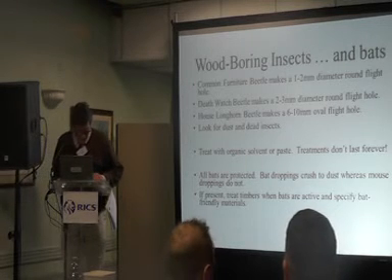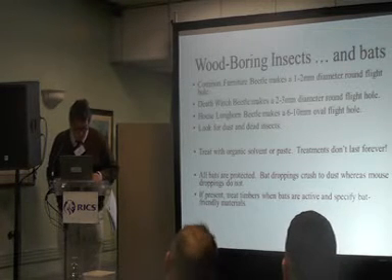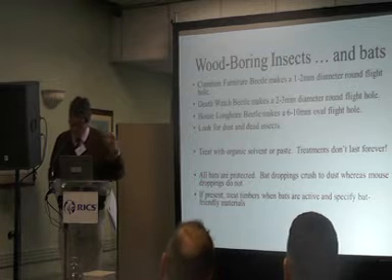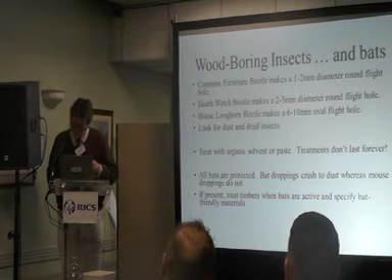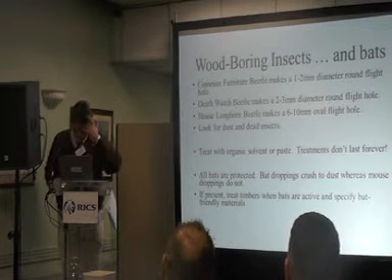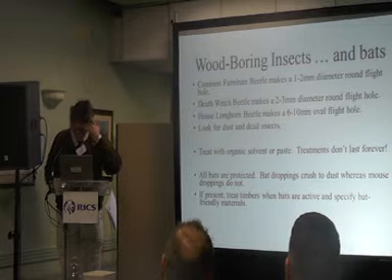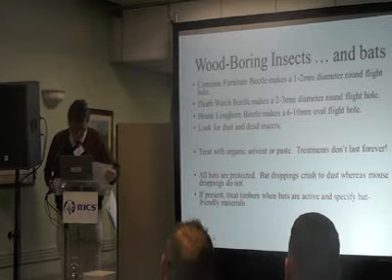Now, if bats are present, treat the timbers when the bats are active, when they can fly about and get away and go somewhere else. They'll come back in their own good time. And specify bat-friendly materials, and Mrs. Google will tell you as much about that as I can.